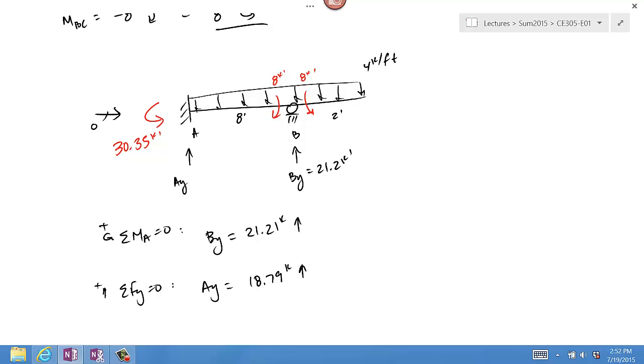Okay, so that concludes this example. Just as a review, it's important that you recognize the settlements that are given. If the settlements for a beam are given as linear displacements of supports, then those would produce at least one chord rotation. If you see a support that is fixed undergo a rotational settlement, then that rotation is actually given to you. It's one of the thetas. In this case, it's theta A.